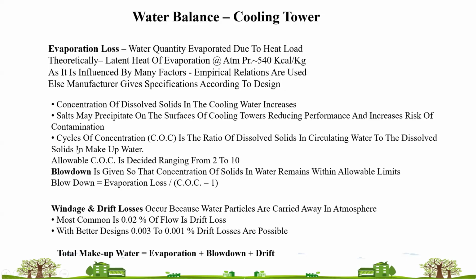Then COC is one of the important terms. COC is cycles of concentration. Whenever your cooling tower water is circulating again and again, it's a closed loop system. There is bound to be dissolving of salts inside the water, and that concentration goes higher and higher.